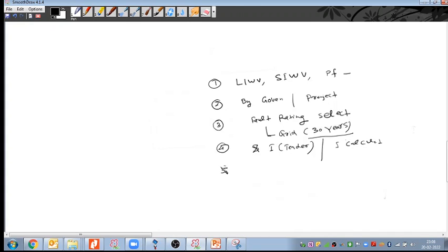And then we discussed that during equipment selection, do not only consider the electrical parameters, we have to see the environmental conditions in which the equipment is going to be installed. So the site environmental conditions like the seismic zone, the ambient temperature, the mean sea level height, all these parameters we also have to review, and we have to take approval from the equipment supplier that the equipment is designed to withstand all these site conditions.